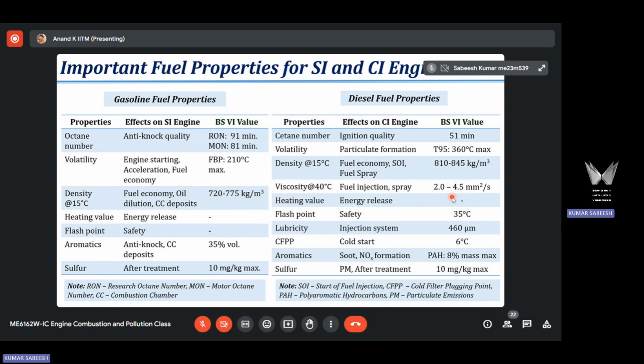When the piston is far away, whatever bowl design you make, the bowl is not taking the fuel spray, right? When the bowl is nearer, it will take the spray. When it is away, it won't take the fuel. So the timing of fuel injection will play a significant role.